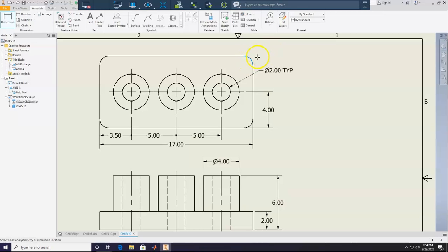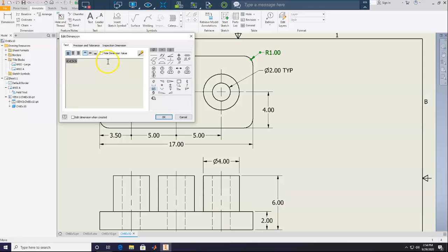You're going to say, it's not working. It's because you're hitting where it's a green dot, and when you're doing a green dot, you're telling Inventor, go from point A to where? Well, you gotta wait for it to click on point B. However, if you just click it when it's a red line, it'll go straight to dimension, whatever that is. Include, and I just keep caps lock on whenever I'm doing engineering work.